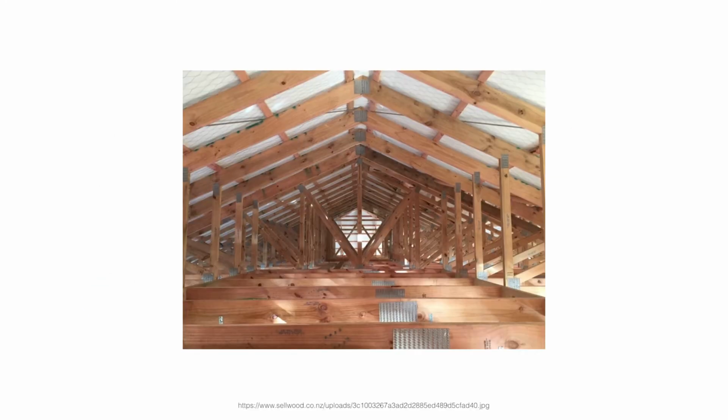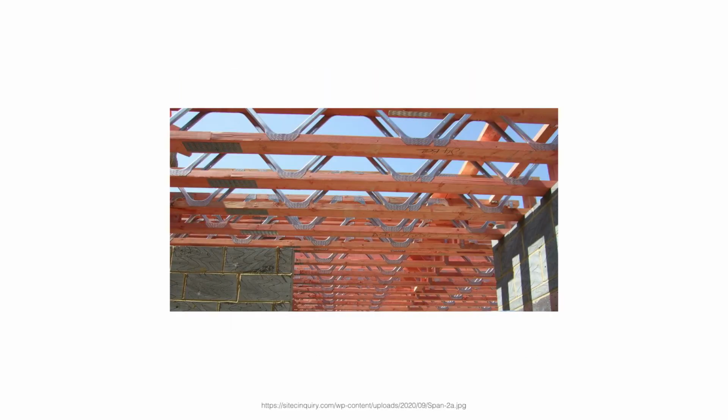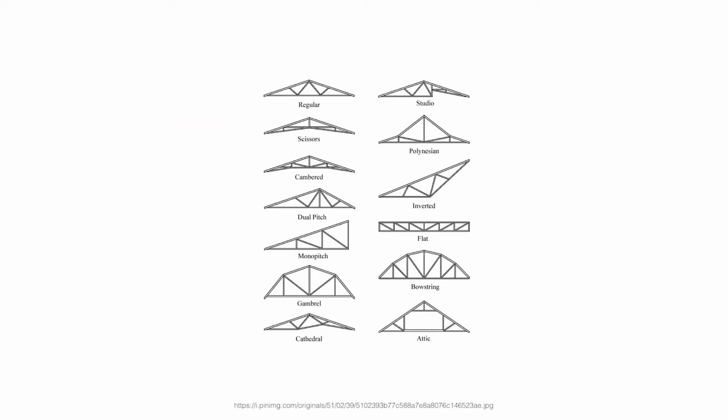Well, the first one is that it makes the attic space unusable. When you're using trusses, it just takes up so much space for the ceiling. It also restricts the designer to having a flat ceiling throughout the building, which can be boring, but it works. The good thing about trusses is that they use triangles, which is a really stable shape.